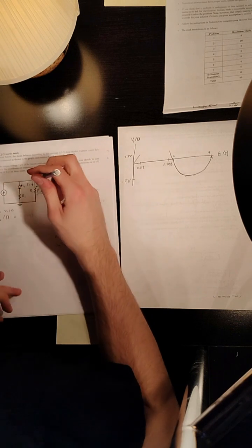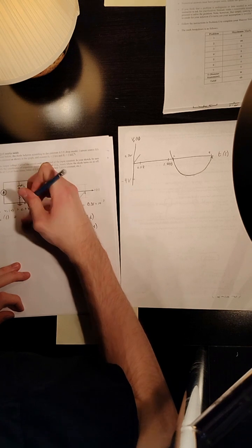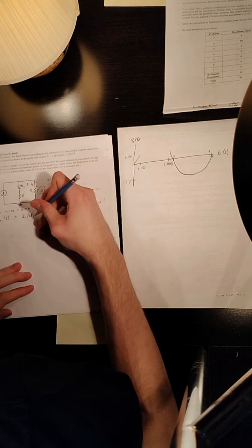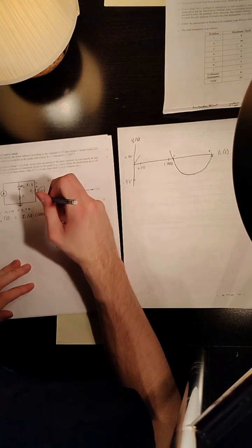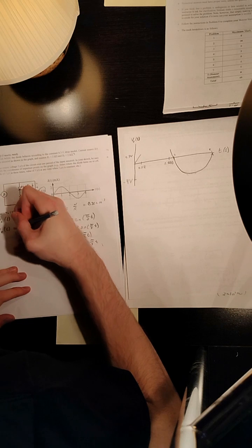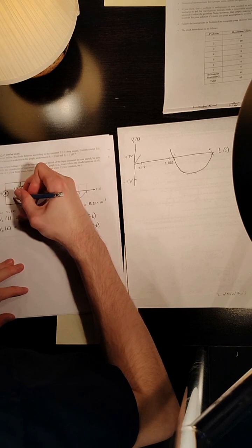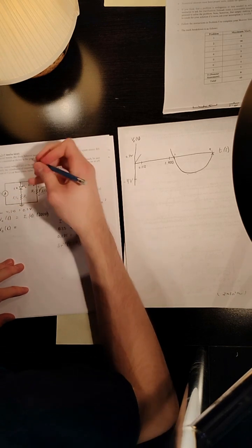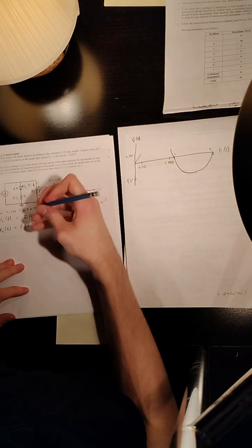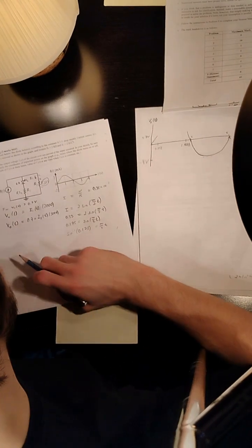Then what we have is, for VO of t greater than 0.7 volts, VO of t is equal to I1 of t times 2000. And then VO of t is also equal to, so this voltage is 0.7, and this is R1 times I2. So VO of t in total is going to be equal to 0.7 plus I2 of t times 3000. Sorry, covering up the page here.